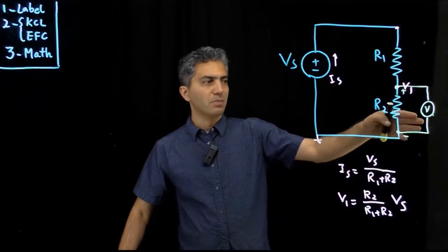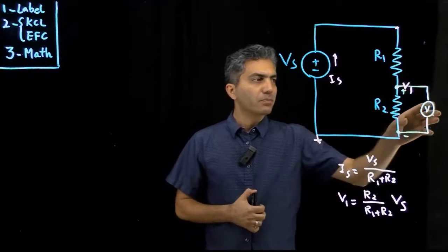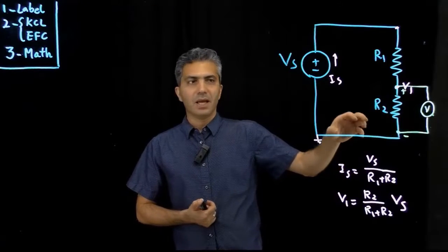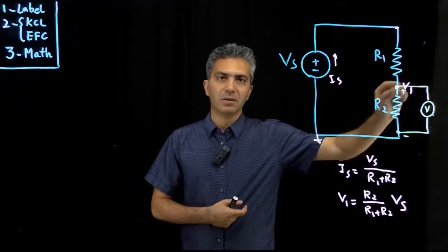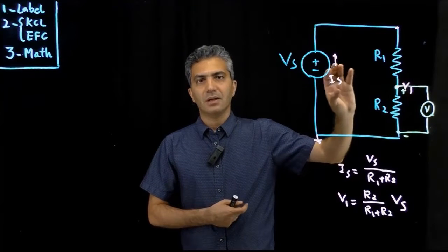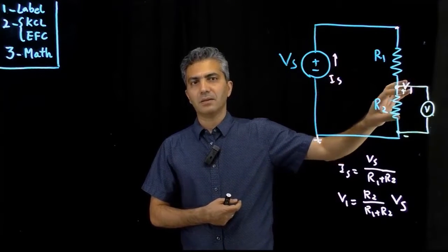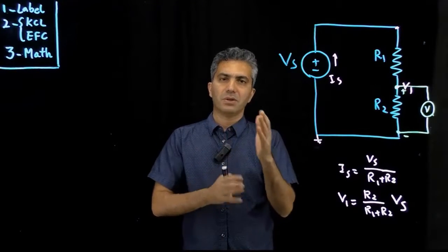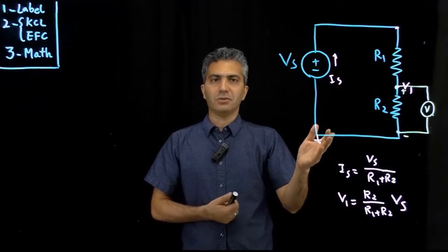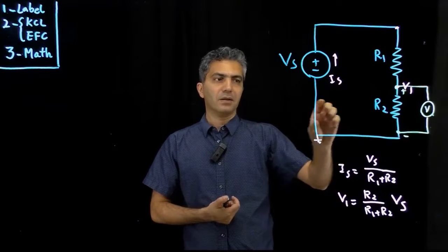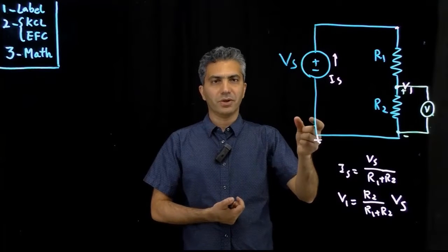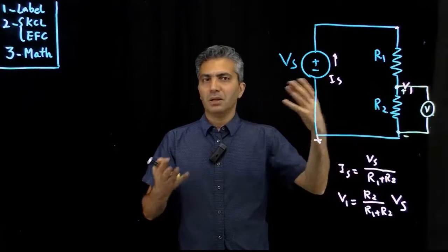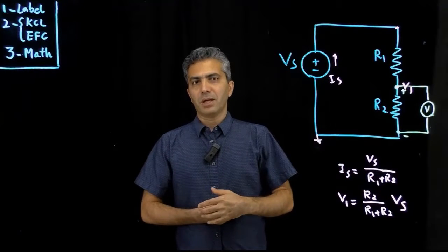In other words, how does the measurement happen? Now, the new voltmeters are all digital voltmeters. And what's going on inside is that the signal comes in, gets conditioned, then it's applied to an A to D device, which stands for analog to digital converter. And basically that voltage turns into a digital number. The digital number then is read into a microprocessor and gets processed and displayed on a display.